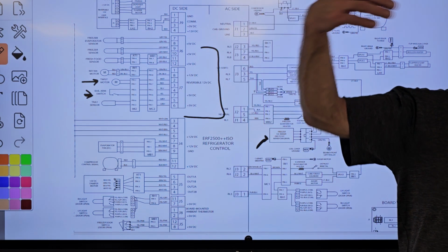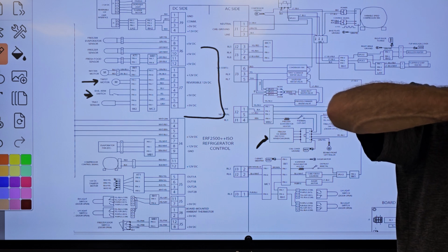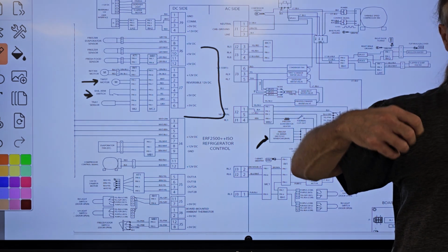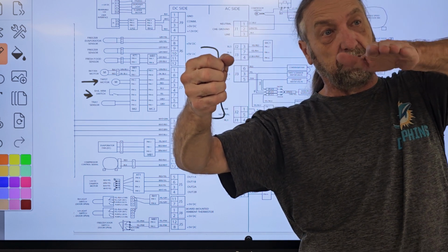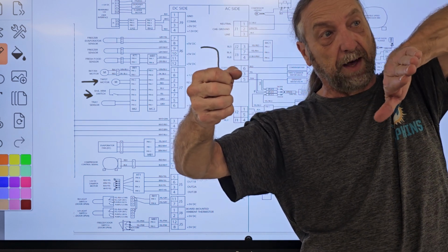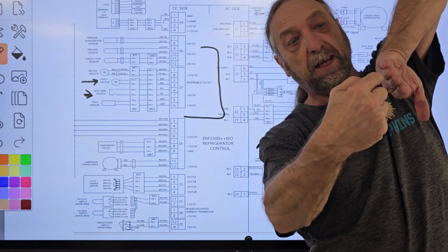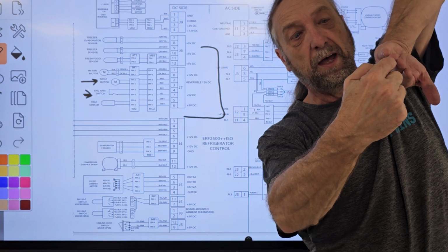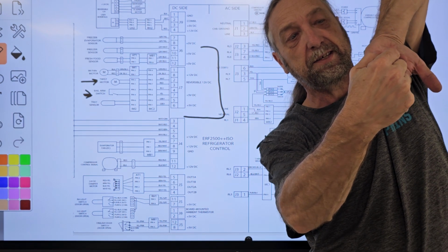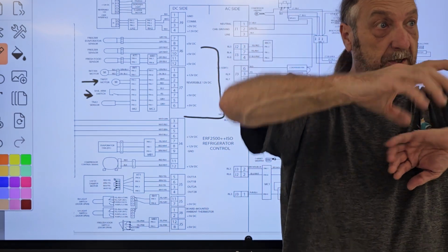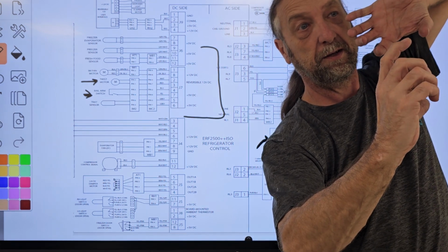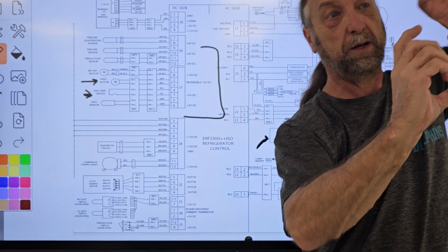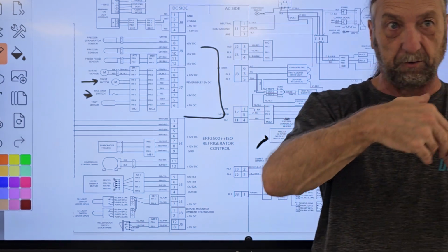Now the bail arm is part of the ice maker, and the switch is inside the ice maker, but there's an arm. When the motor takes this tray horizontal and goes to flex it, there's a piece of plastic here that catches part of the tray, but the motor's still twisting it, so that's how the tray actually twists. It holds one end, but the motor's twisting the other end. And then when it pauses and stops, that's when it reverses and goes back up and fills with water.